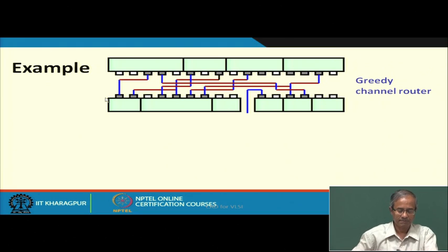This is an example channel. Let us say this is a typical snapshot of the standard cell design style. Here I have shown 4 cells which are placed, here also there are 6 cells which are placed, and this connection I am showing in between may represent a feed through cell, but I am just showing it like this without showing it in a closed rectangle. So, this allows a vertical connection to go through it.